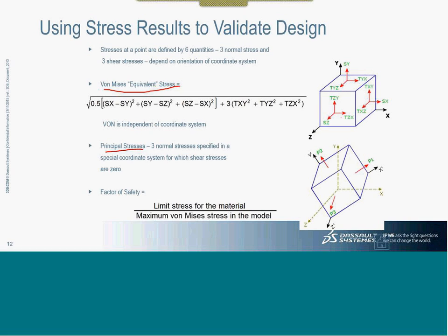If you take this example, say this cube, and I have applied the force in this particular X direction, they are called planar stresses. So assuming this force is in the X direction, this divided by the cross section in this plane gives us stress in the X direction, right? Then we have stresses in the Y direction and the Z direction. So these are nothing but planar stresses in Y and Z direction.